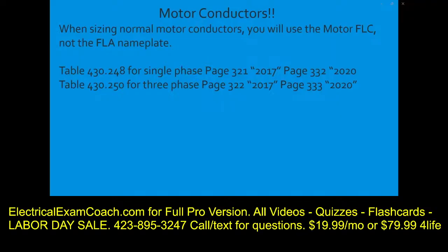When we go to read this table, we're going to read it just the same. We start on the left-hand side. It's going to be our respective horsepower. And then coming across the top are our voltages. Again, I want to warn you, make sure that whatever the question states, you choose from that voltage. So even if it doesn't make sense, if they put 230 volts on a three-phase system, just do whatever the question states, okay? Don't try to change the reasoning there because it's very easy to do.